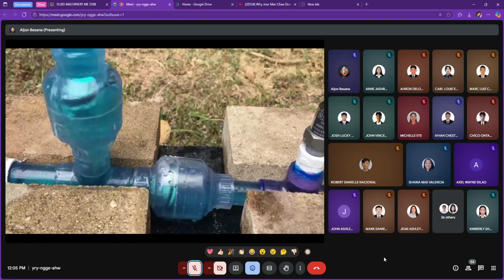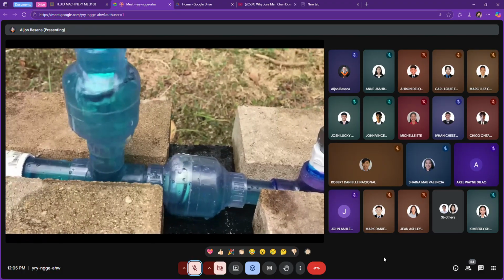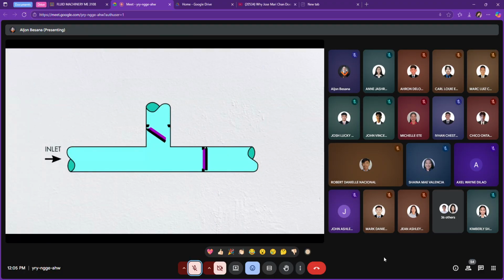Let's walk through the path of the water to understand how it works. First, as the waste valve opens, water flows into the pump and immediately out the valve. But as it picks up speed, the flowing water eventually forces the waste valve to slam shut. Now the water is stopped in the pump. It had kinetic energy, but now it doesn't.